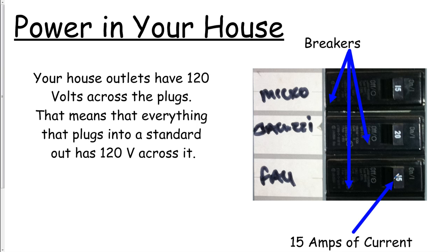You might see a 30 or 40 amp breaker, but those usually take up 2 spots. And the 30 or 40 amp breakers would be like your air conditioner, your hot water heater, your dryer, your stove. But 15 to 20, these are, you're looking at just normal rooms, such as the lights or the outlets. I have one specific for my microwave and one specific for my jacuzzi, but here's the whole family room on one 15 amp breaker.